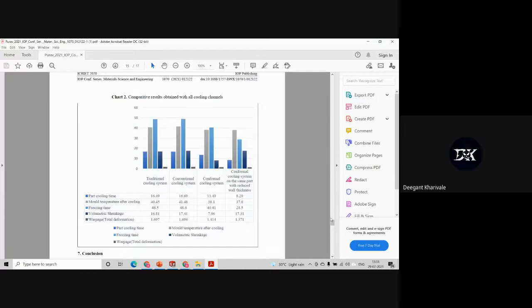Yes bro, first the injection happens. After the plastic fills, the punch die, which is a moving die, will mate with the female die and cavity die. The plastic will take the appropriate shape, and then packing happens. After that, during the packing process, cooling takes place simultaneously. While the packing process is going on, cooling happens.